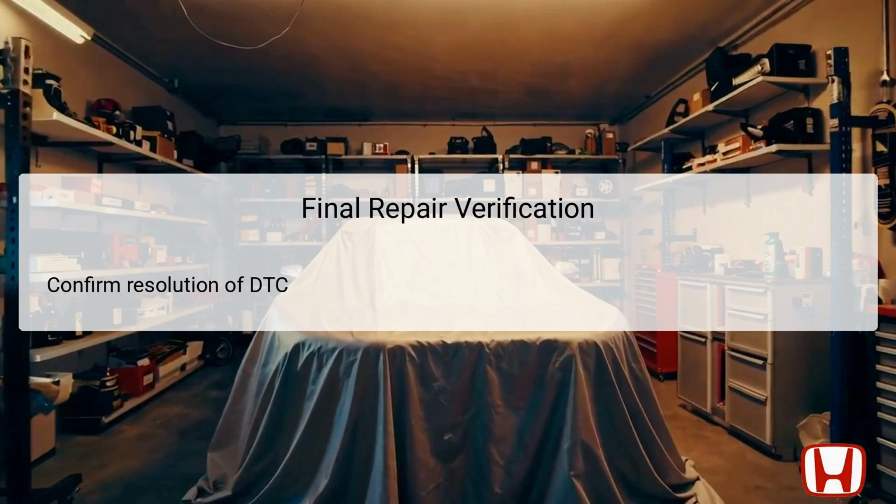After completing all necessary troubleshooting steps for the DTC B1C55, it is important to conduct a final repair verification to ensure that the issue has been rectified. This process involves rechecking the resistance values and ensuring all connections are secure and corrosion-free. If any repairs were made, such as replacing a thermistor or repairing a circuit, you must monitor the system to see if the DTC reappears.